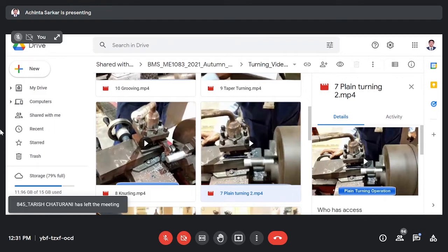Then another thing finally, sir explained the cutting velocity or cutting speed. Okay, so cutting velocity is one important cutting parameter. It is one type of tangential velocity, and it can be defined by this formula: pi DN upon 1000. Pi everybody knows is a mathematical constant. D is the diameter of the workpiece on the machine. N is the number of revolutions per minute.